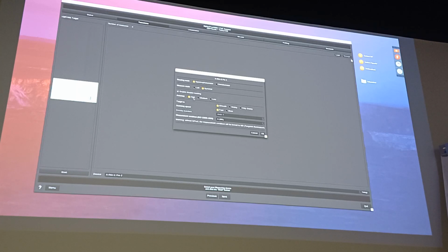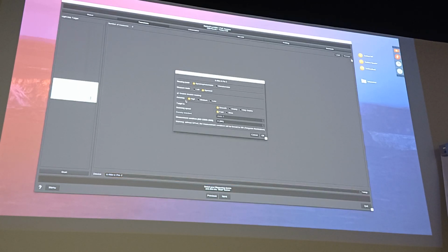So it will be better to enable the double reading to make sure not to have something which is bad. And the accuracy depends once again on the type of media you are using. If you are really struggling to get the two same measurements, you will always get an error message. Then you can try to decrease the accuracy to medium or to low.